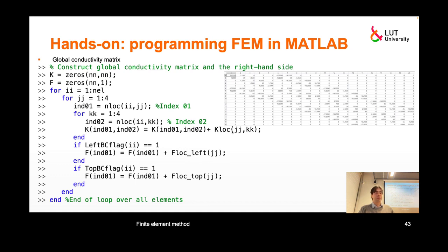Matrices, and there is this sum because certain components of the global matrix may take contributions from different local matrices if it's associated with a node that is shared by elements. Most of the nodes are shared by elements except for the four corner nodes, and then there will be contribution from all elements which have those nodes.